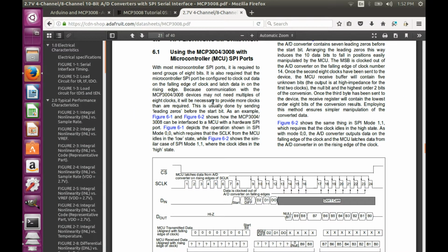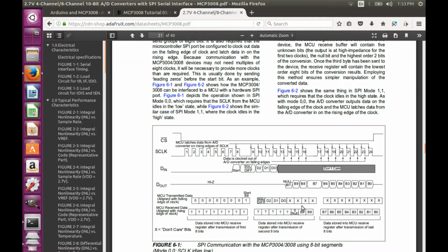recommends the following communication with the microcontroller unit. It consists of 3 bytes, with the first 7 bits being just zeros and the last bit being the so-called start bit. And then you have 2 bytes of transfer that sends what we want to get and gets back the results. However, this means that 7 bits are pretty much wasted time that reduces the sampling speed.